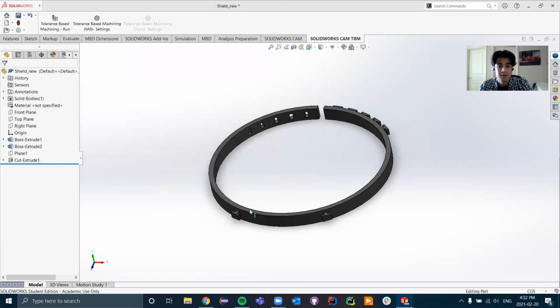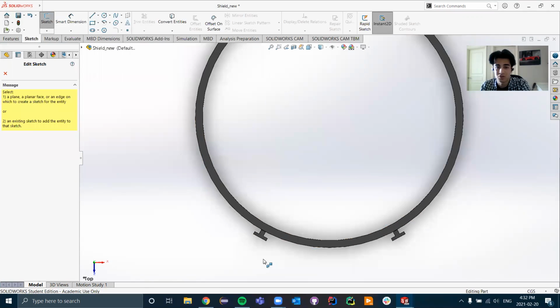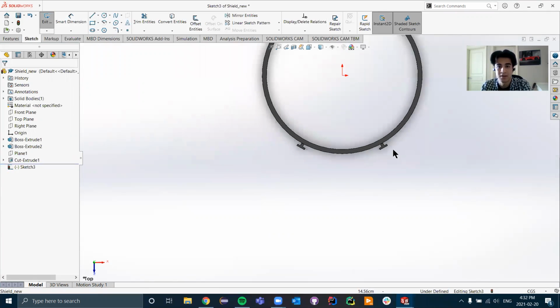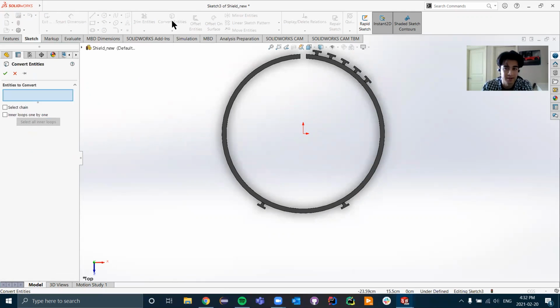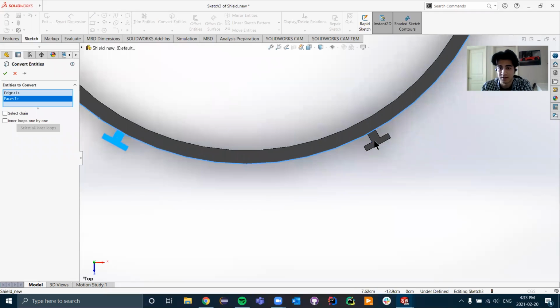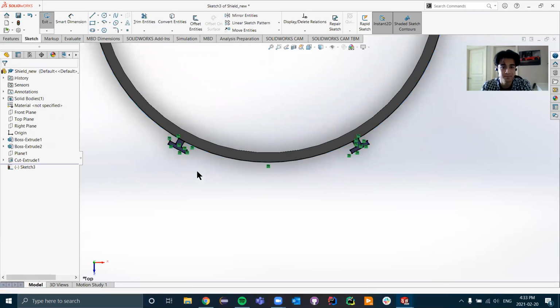Now, the first step would be to actually make use of the geometry that was provided to us. So what I'm going to do is I'm going to fix our frame as demonstrated. I'm going to create a new sketch, but this sketch is going to be on top of these front connections here, and you'll see why in a second. Now, we currently have no geometry to actually base our sketch off of. We have no lines within our new sketch. So what I'm going to do is I'm going to use the Convert Entities tool. And if you remember that, it essentially projects anything from another sketch to your current sketch. So I'm going to click this line right here and these contours right here. Remember that we can click faces and it'll essentially trace out the edge and bring it up to what we have here. And there we go.